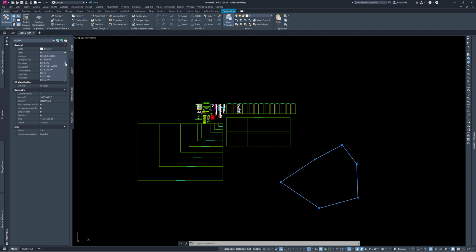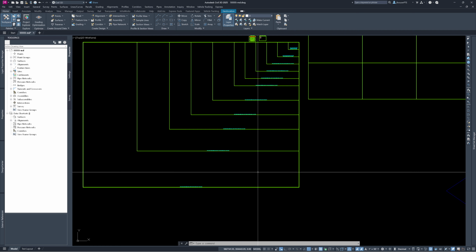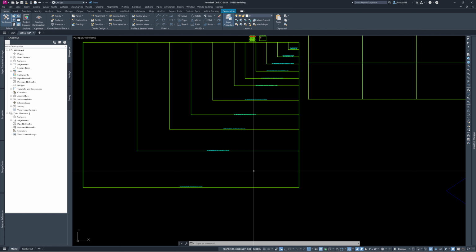All right. Now, what's important is all of these green squares here have already been adjusted for the viewable drawing area on our typical plot sheet, 24 by 36, and they list the scale. So at 200 scale, this is how much a 200 scale sheet can show. So let's say, in this case, we need to show the entire plot property.